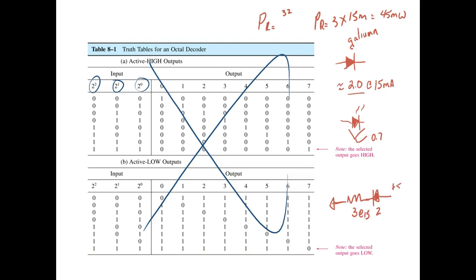My output for a high for standard TTL is around 400 microamps, so I don't need an eighth of a watt for that either. I can actually go smaller. Sooner or later they integrate them in a pack, so we have what we call resistor packs.